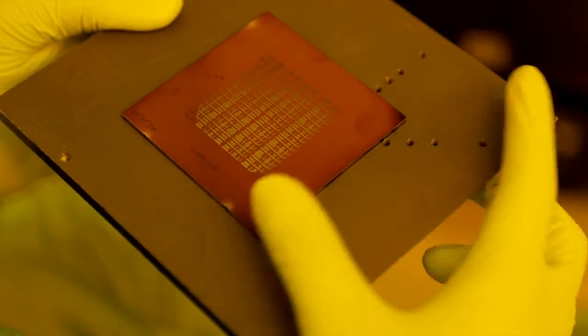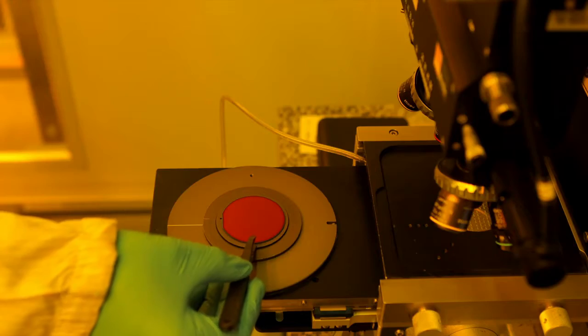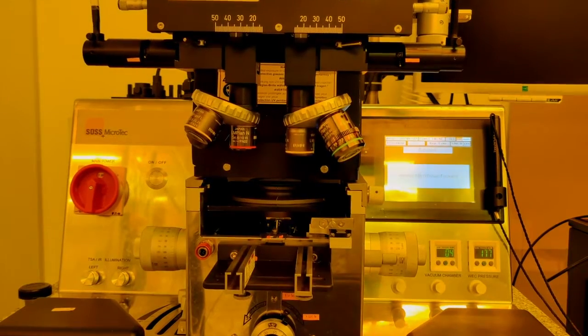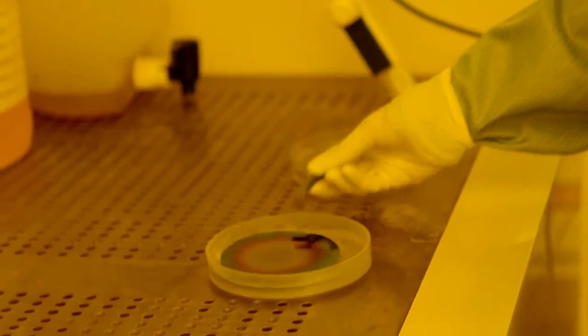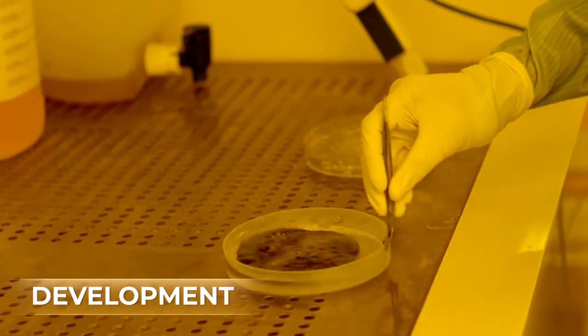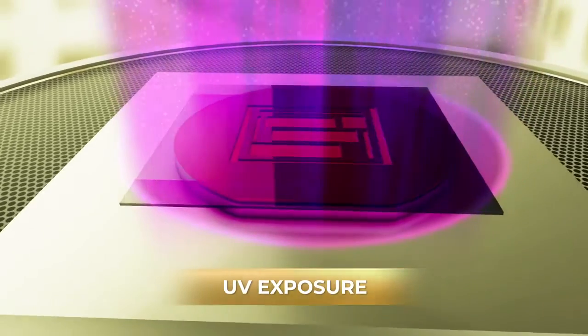After the PR has dried, the coated wafer and the mask are loaded onto a mask aligner and illuminated with UV light. Only those areas that are not masked off are exposed. After exposure comes development. The wafer is dipped in a chemical that dissolves our special chemical, the PR, only from those regions exposed to UV light through the mask.